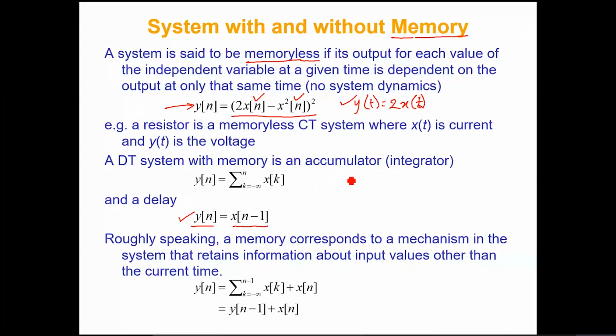Now we can give examples of any discrete time or continuous time memory or memoryless system. One of the most common memory systems that you computer engineers especially come across is an accumulator system. If you have any system which just accumulates, or keeps adding on, all the inputs till present time, that will be an accumulator system.